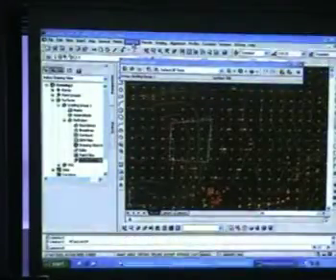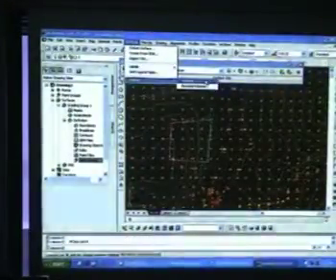Okay, I'm just going to run through the volume calculations quickly with you. Just click on volume. Then this composite volume window appears. This uses the composite volume method, which is very easy to use. We start off with the first icon. Click create new volume entry. What you get is a line underneath here. All you need to do is specify a base surface and a comparison surface. Base surface means your original level. So let's say we select OGL. And for the comparison surface, I'm going to select Learning Group 1. You just click anywhere outside and it does the calculation for you. Learning volume 2 will appear here.